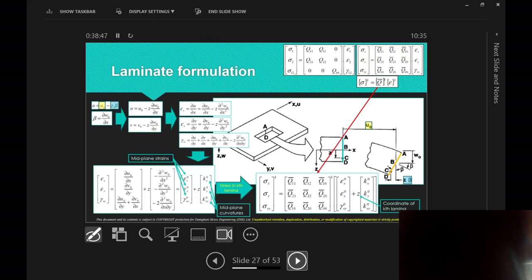So if I know where the mid-plane goes, that point at Z essentially is U0, take away Z, or its location from the Z-axis, times beta, beta being the angle. Okay? So we always find the next location of the mid-plane, and then find the rest of the cross-section based on that. The beta is essentially the angle, or the rotation angle of the section.